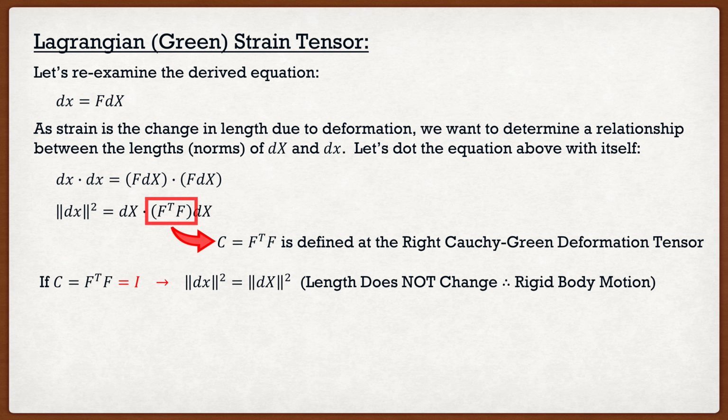So because of that, we're going to go back to C, and we're going to use its actual definition of F transpose F. And what we're going to do is expand out what we get, and we get the following, where C is equal to I plus nabla u plus nabla u transpose plus nabla u transpose multiplied by nabla u.